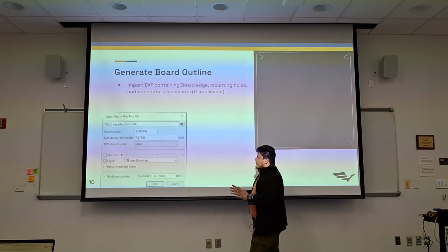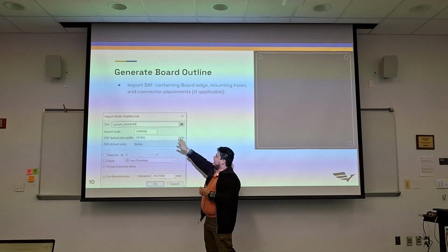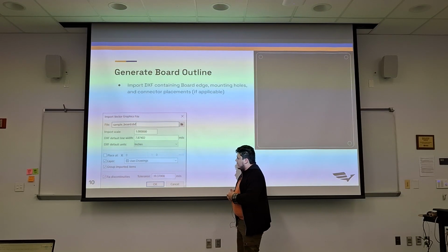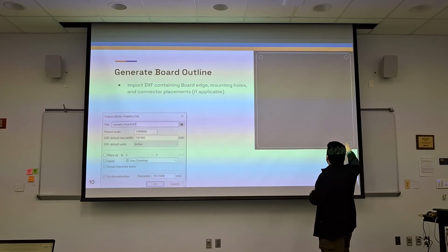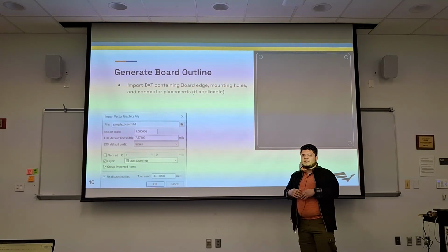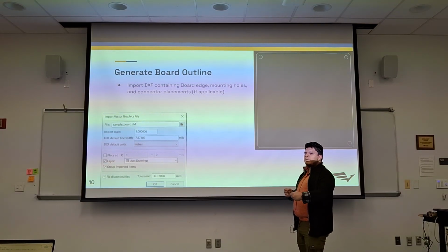Industry standard, normally the DXF is in inches, so you want to make sure that you're importing inches, and hopefully it should be to scale, right? Work with mechanical, assuming they're going to give you a DXF if it's a board that needs it. That's going to give you the outline and the place for the mounting holes. I think currently we're doing mounting holes as a mix of edge cuts. I'm not sure if there's a mounting hole part in your library. If not, that might be something to look into as well.